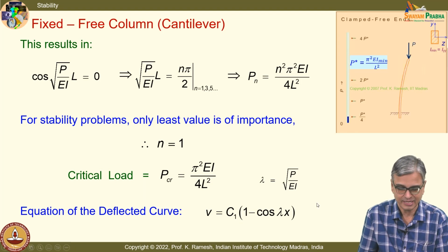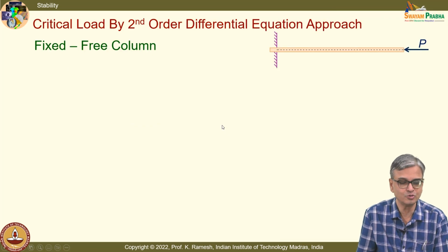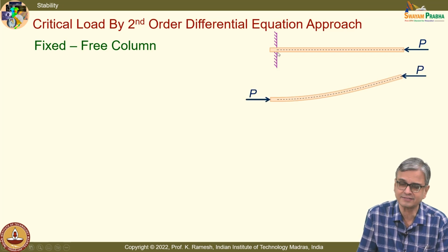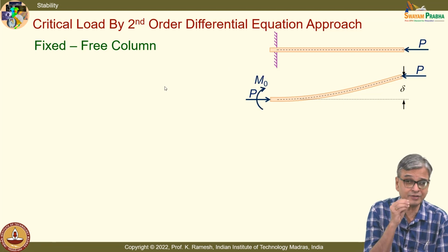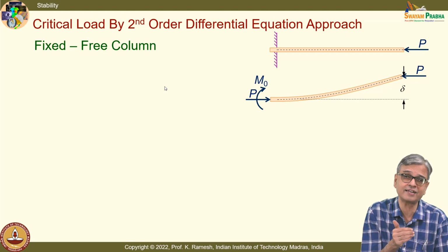Okay. See, there is also another approach which is usually adopted by civil engineers. They use a second order differential equation. It is discussed for a fixed free column. You have enough background to do that, and this is a statically determinate problem. Whereas, if you have hinged, even hinged is statically indeterminate. Hinged roller support is statically indeterminate. So, all the other problems are statically indeterminate.